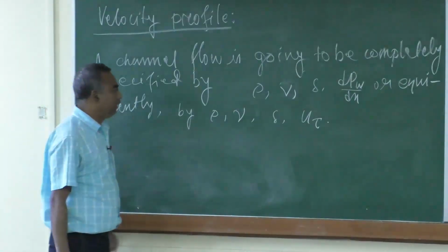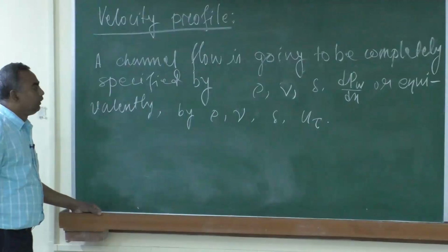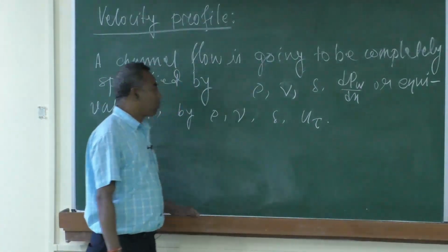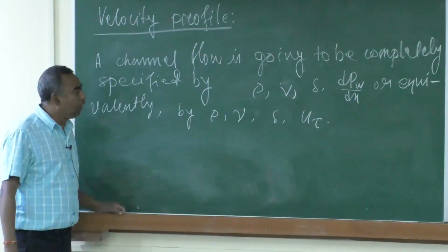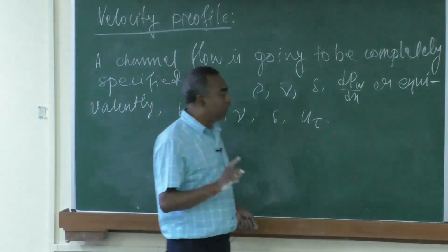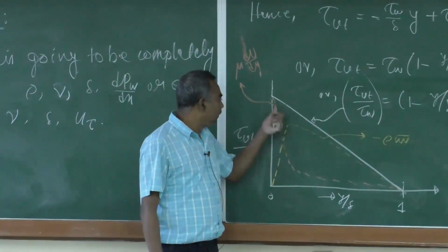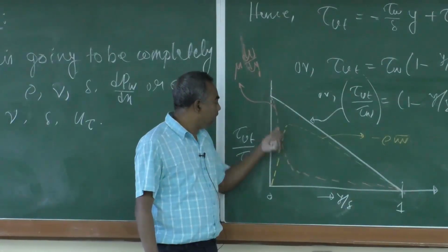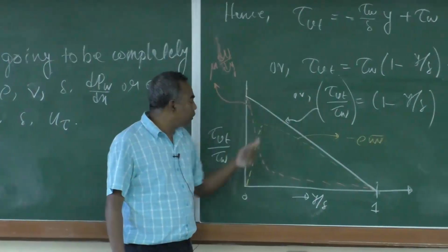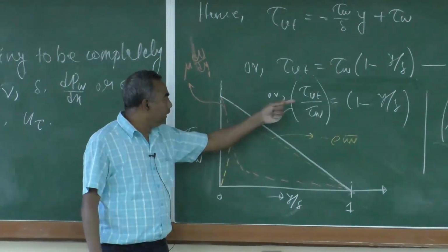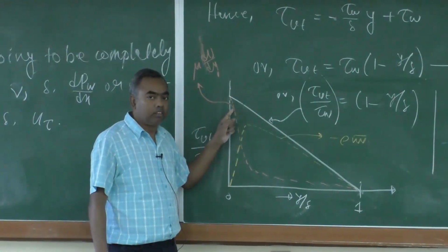So, here before we proceed, some discussion is needed. What is u tau? U tau is known as friction velocity. Near the wall, we need to figure out the right length and velocity scale, because near wall dynamics is governed by this equation, which shows that very close to the wall, the total shear stress is mainly dominated by viscous shear stress.